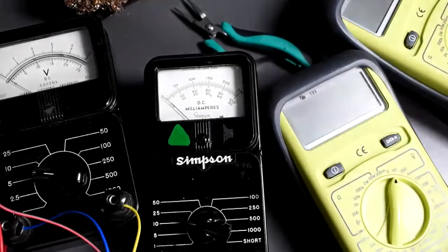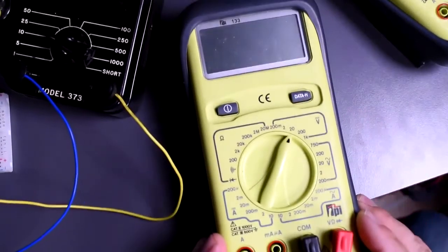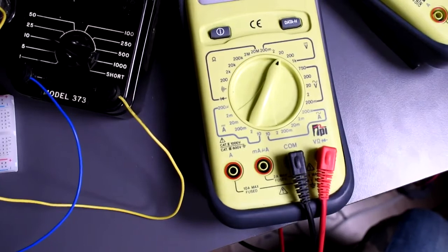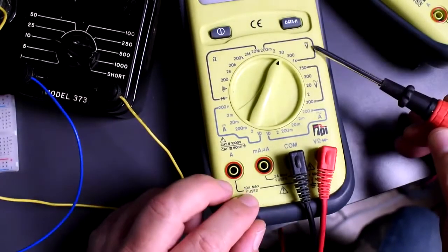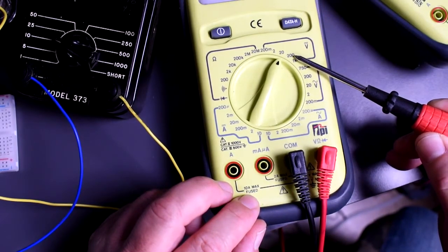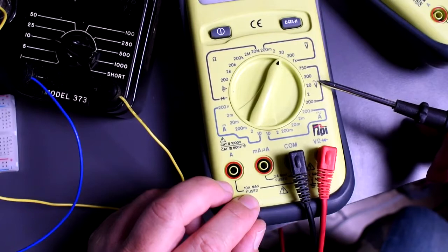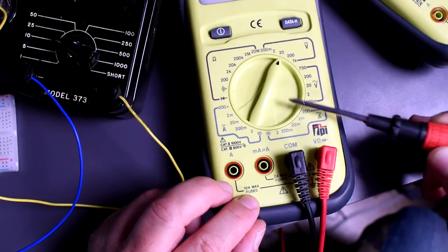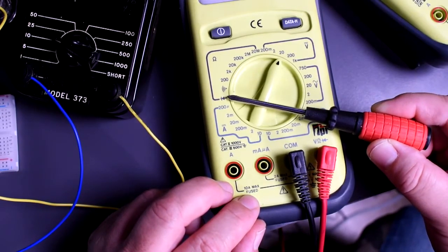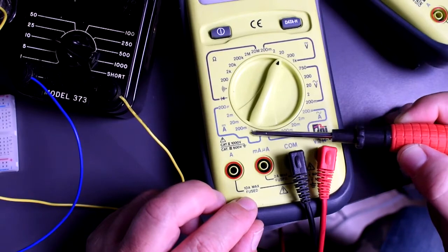Let me zoom in on the real digital multimeter. We do have those here. All right, so here's the DC voltage, and the ranges are 1 kilovolt, so that's 1000 volts, up to 200 volts, up to 20 volts, up to 2 volts, and so on. And then there's the same thing for the AC voltage. Then there's AC current. Also, we have resistance, and here's a continuity meter and diode tester. I'm going to show you some cool stuff with that today. And then there is the ammeter section right here.